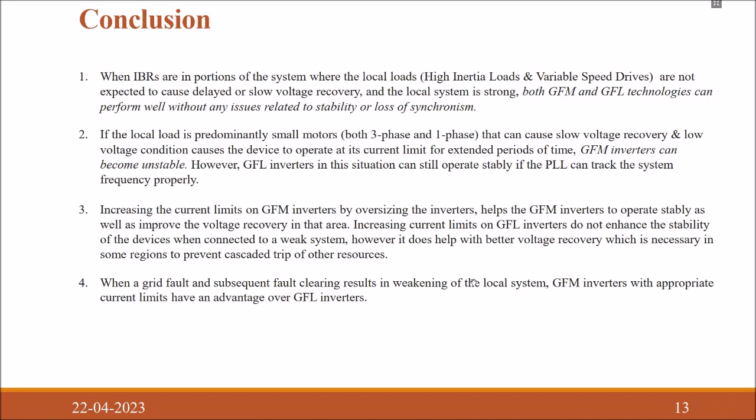However, if we increase the current limits of GFL, it will not enhance its stability in a weak system. However, it will help in having a better voltage recovery, which is necessary in some situations where we have to prevent cascaded trips, but it will not enhance the stability of the device.